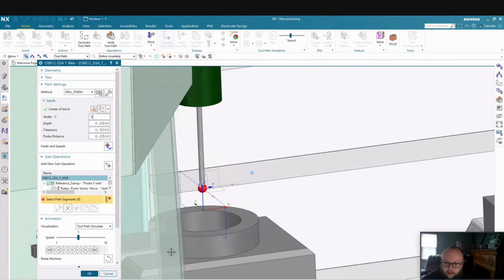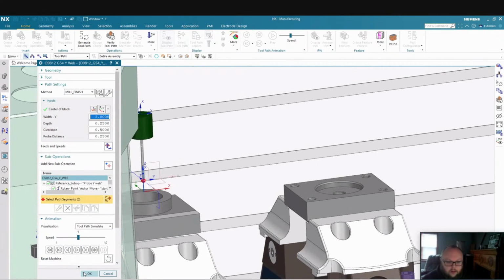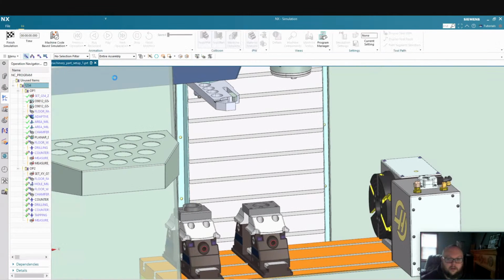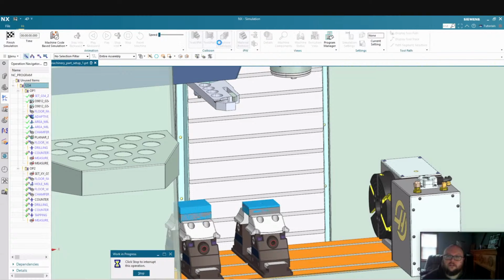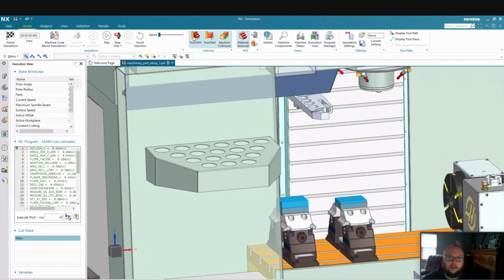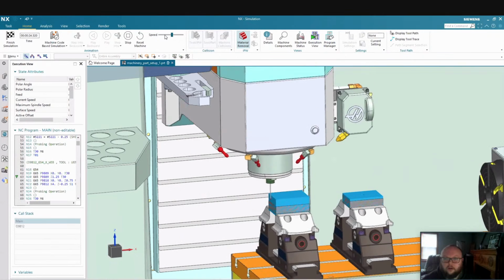And as soon as I change that value, yep, I should have looked closer when I was making my tool paths. Regenerate that. Now it's going to program the proper width of that part. And we'll jump back in and do that machine simulation again. I had my collisions turned off. Well, maybe I didn't, so I would have been able to catch that. But let's go ahead and post out that code, just get that warning message out of the way. And now we'll play this. Let's get caught up to where we were. There's X.